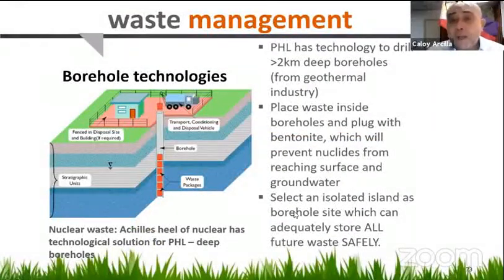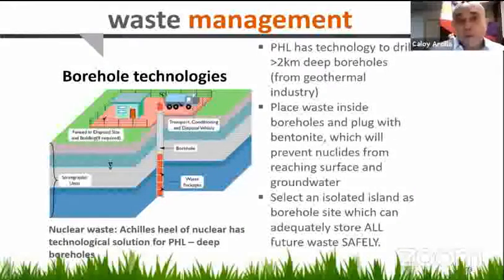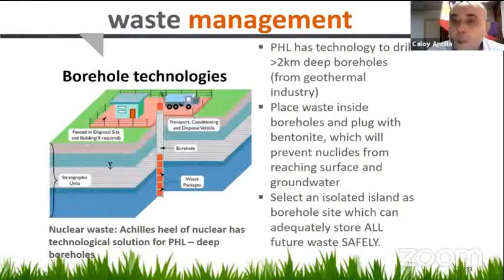Now, the waste management. Where will you put the nuclear waste? Fortunately for the Philippines, we are number two in the world in geothermal. We have the technology to drill boreholes greater than 2 kilometers deep. So my proposed system for disposing of nuclear waste is to put the waste inside boreholes and plug them with bentonite, which will prevent nuclides from reaching the surface and groundwater.